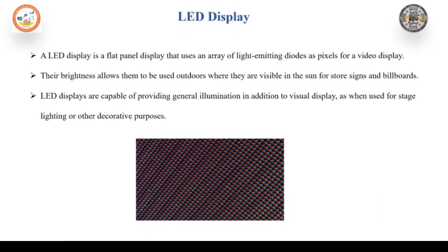LEDs are available in different colors, as I mentioned. They need moderate power and are used where low DC power is available. They occupy a small area. LED devices can be driven by transistor-transistor logic, that is TTL, whereas gas discharge devices need intermediate transistor stages to allow them to be driven by 5-volt TTL.